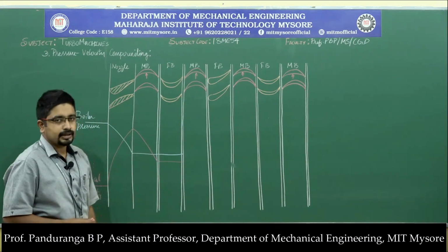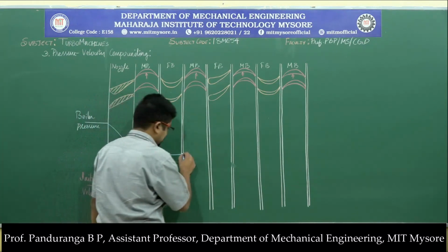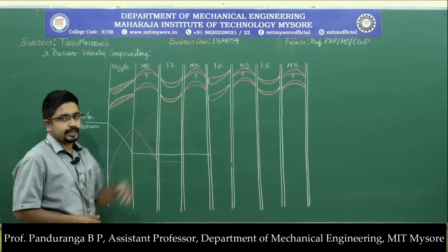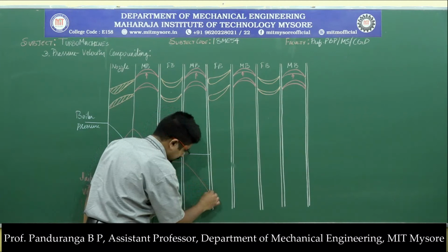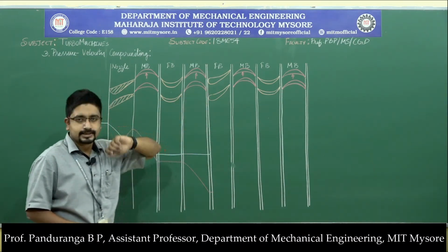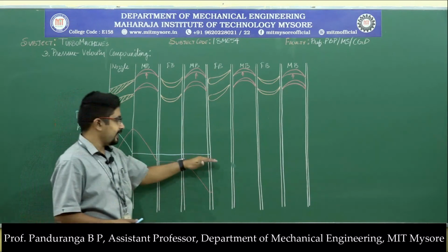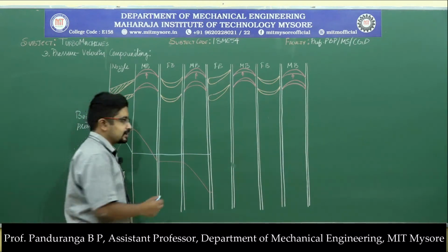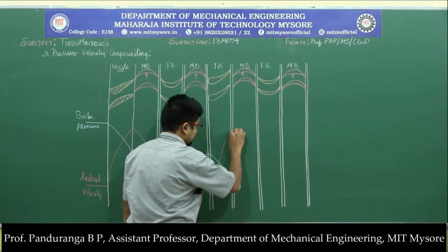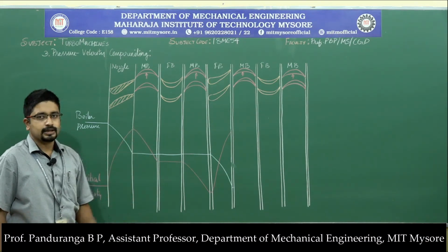Then we have the moving blade, where if you observe the moving blade, it is symmetric over the central axis, and because of that the pressure remains constant as it passes through the moving blade. But the moving blade absorbs kinetic energy, and because of that the velocity of the steam reduces and reaches its minimum value. Now it passes through the next row of fixed blade, which are aerofoil in shape. So here the pressure energy gets converted into kinetic energy. So relatively high pressure which is entering this fixed blade will lose its pressure energy, and the pressure energy will be converted into kinetic energy. So the velocity again increases. The velocity of the steam increases to its original velocity when it was coming out of the nozzle.